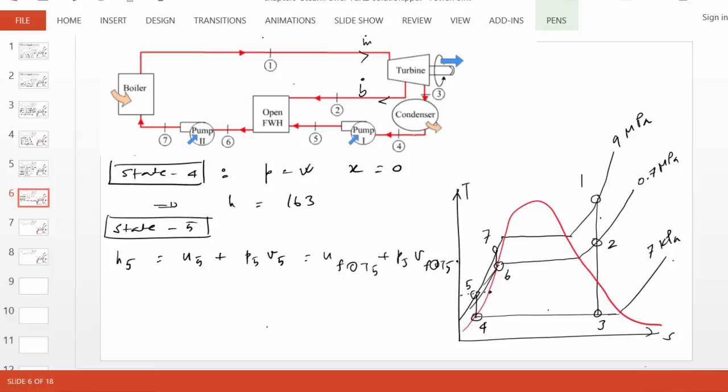That's the compressed liquid model, right? Now T5 and T4 are equal. Why? Because if you recall, in an isentropic situation for liquid, entropy is a function of temperature alone. So if entropy doesn't change in an isentropic case, therefore temperature doesn't change.